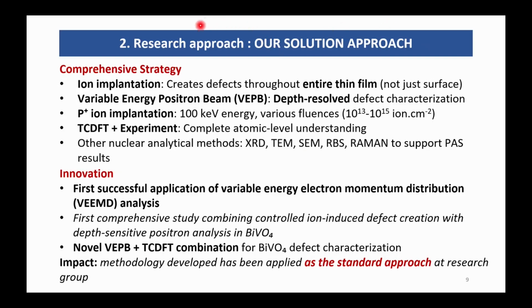So with our solution approach, we used a comprehensive strategy for ion implantation. We can create the defects through an ion beam, not just at the surface as with other conventional methods. Second, we use a variable-energy positron beam at the positron facility at Dubna, so we have depth-resolved defect characterization.